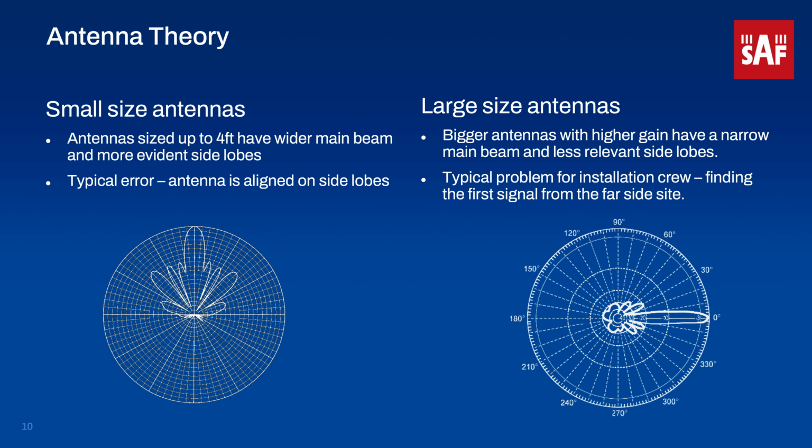Antennas typically have this kind of radiation pattern where they have a single main lobe, into which direction the signal is transmitted with the highest gain, and then there are side lobes. Those side lobes are actually what we will be measuring on those radio links from the ground level.